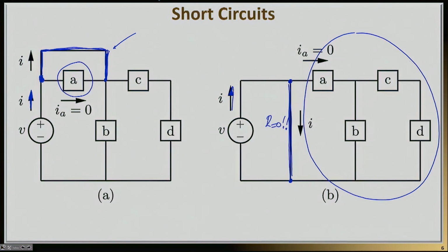We'll discuss resistance in more detail later on, but I'm sure that you all have an intuitive understanding of that. Essentially, that means that this current I could be simply too high. And if this current I now is too high, because you're forcing this current to go through a path of practically zero resistance, you may be up for some very, very unpleasant surprises. Something may get burned, cause fire, or even worse, cause injury or death. So you need to be very, very careful where intentionally you're introducing short circuits to bypass devices. You may actually create a dangerous condition.